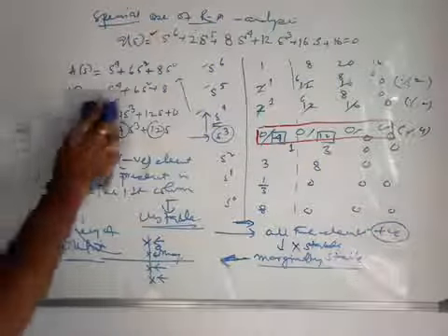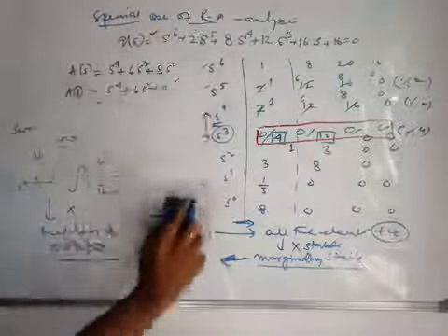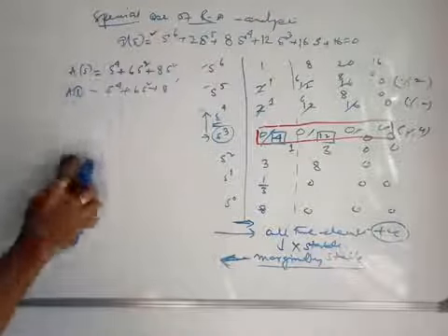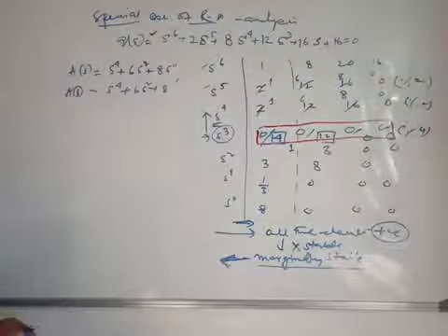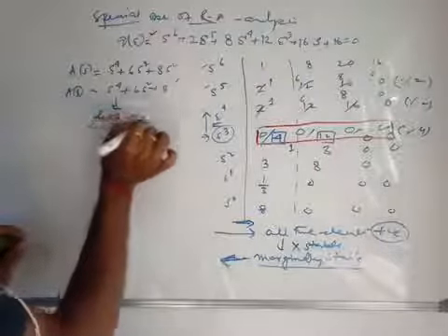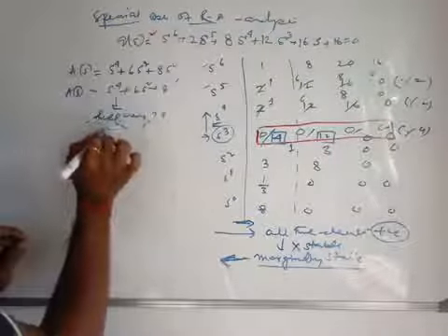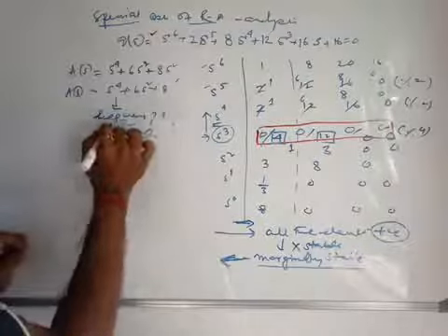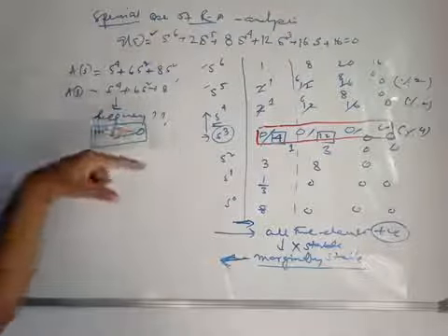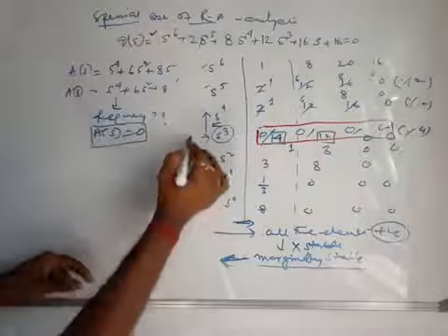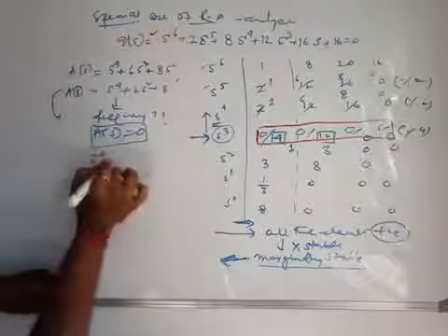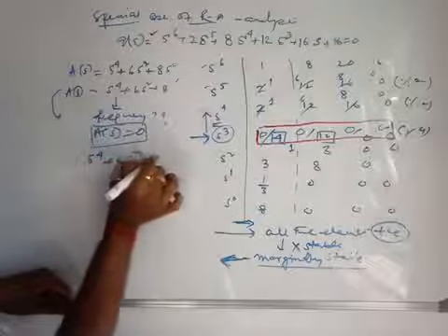So this part I am just removing, and you see there is an auxiliary equation, and this is a fourth order equation. So to get the frequency, we have to make the auxiliary equation equal to 0, because this is a condition where the pole locations have also changed due to overcoming of this stage. So what you have to do: s to the power 4 plus 6s square plus 8 must be